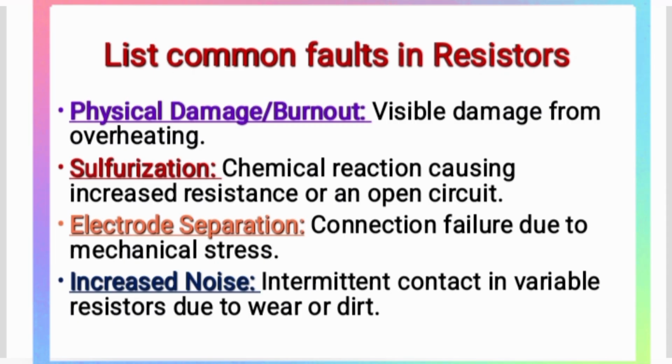4. Physical damage or burnout, visible damage from overheating. 5. Sulfurization, a chemical reaction causing increased resistance or an open circuit. 6. Electrode separation, connection failure due to mechanical stress. 7. Increased noise, intermittent contact in variable resistors due to wear or dirt.